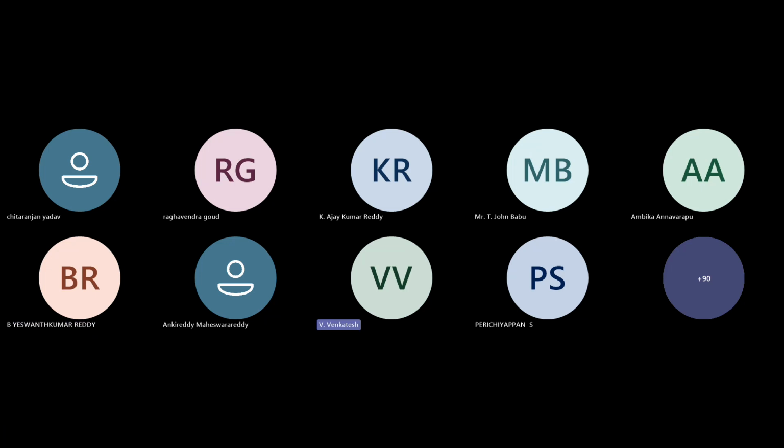I was not able to print the upcoming layers because it started to block the nozzle. I also don't know the technical reason. Later, after a few days, I purchased 80,000 molecular weight PCL, and I was able to print multiple layers. Surprisingly, I printed a sample 1 inch, nearly 25 millimeters, in height with 12 millimeters of diameter. So molecular weight of the polymer also plays a major role in printing.